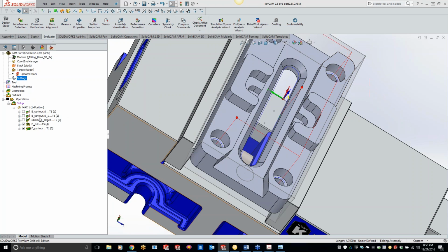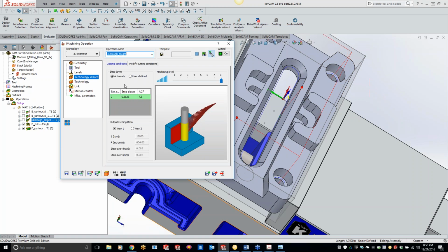See 2 or 3 passes. So yeah, absolutely. If you want to do 5 passes, I can type in 5, and we have 5 passes, doing a step of 0.3531 right there. If we want to do it in 1 pass, it's not going to shank out. So right now it's automatically going to put 2 passes in there for me, one at 1 inch, one at 0.7656.